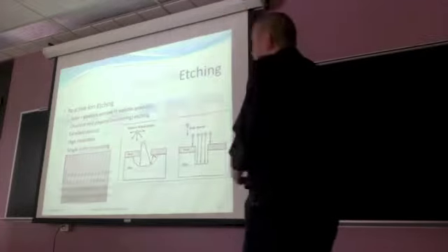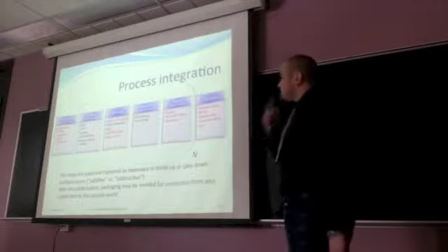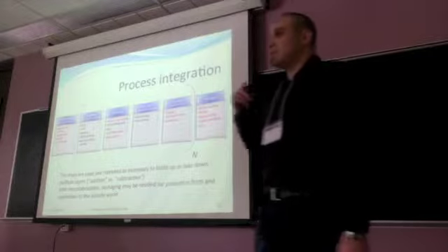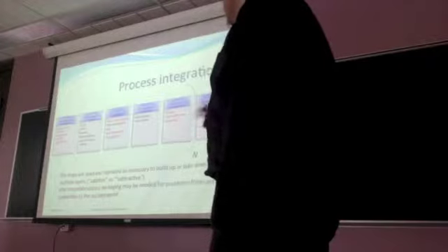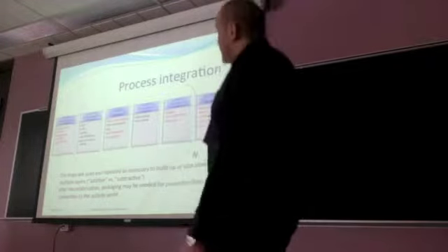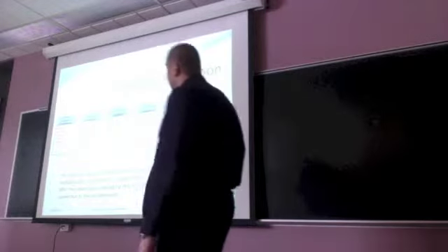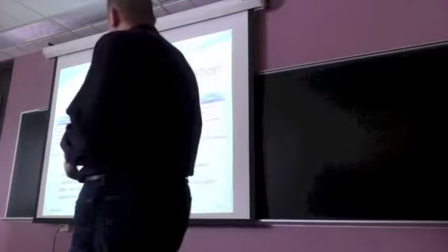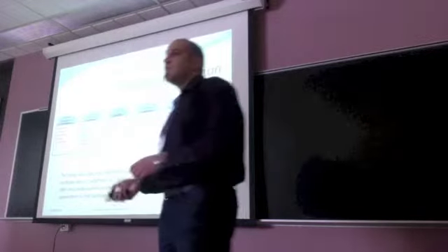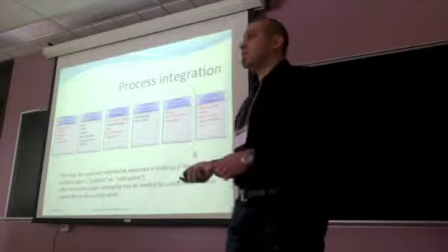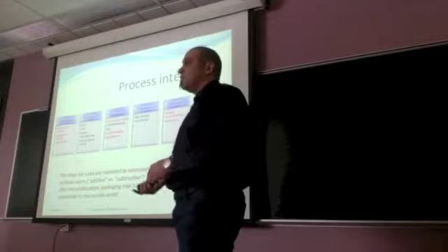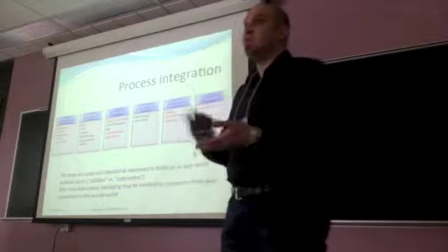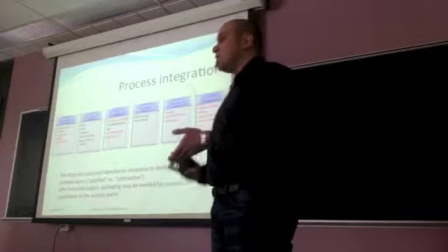So on this slide, I summarize the microfabrication techniques in 6 categories. The processes in red color are not discussed in this presentation. But for example, here the first one, substrate preparation. So we need to clean, and cleanliness is very important for applications when you want to fabricate transistors or for epitaxy. In epitaxy, cleanliness is very important because if you have any defects, it will affect your growing layers.